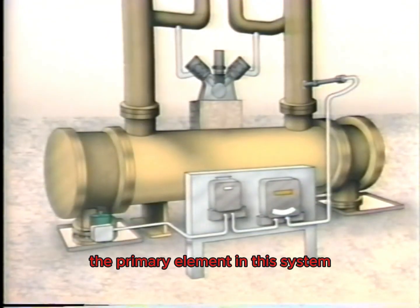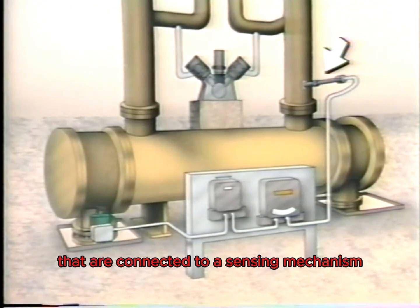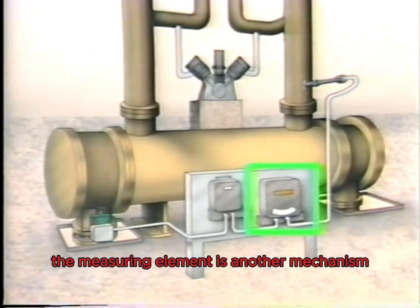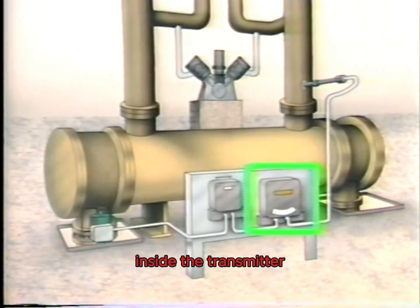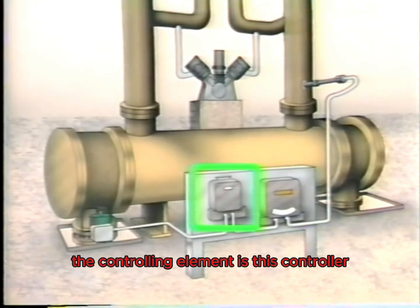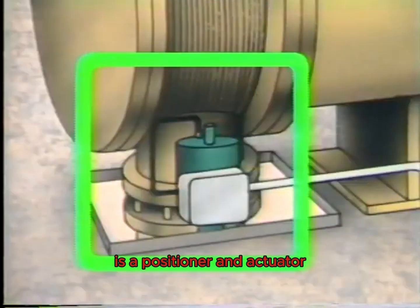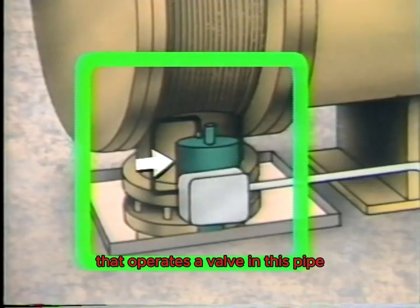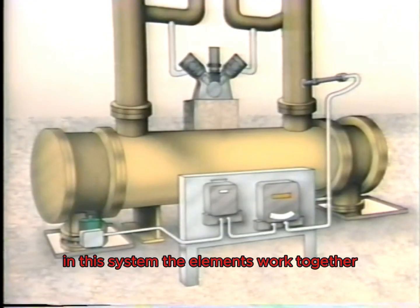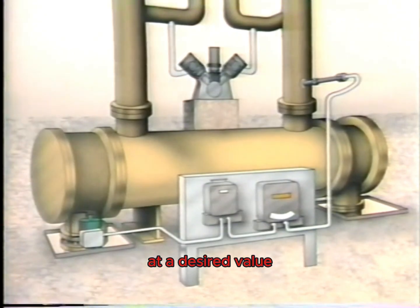The primary element in this system is a temperature sensing bulb and capillary tube that are connected to a sensing mechanism inside the transmitter. The measuring element is another mechanism inside the transmitter. The controlling element is this controller. And the final control element is a positioner and actuator that operates a valve in this pipe. In this system, the elements work together to maintain cooling water temperature at a desired value.